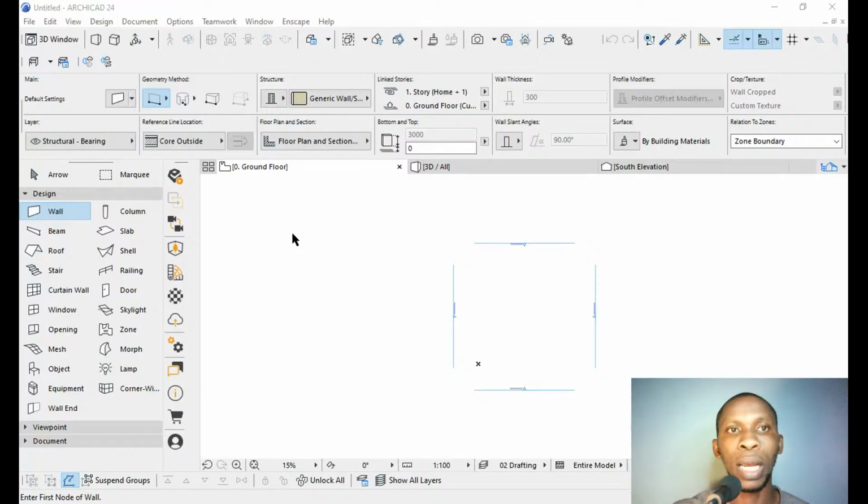So I choose black, and I'll go down to the second one, and I'll make it 0.5, and I click here. Then I go down to the next color, and I make it 0.3. So I want to work with just those three tools. When I began to edit it, you see it changed from architectural to custom. That means you are actually customizing the pen you are working with. All right, so now we're going to click OK.